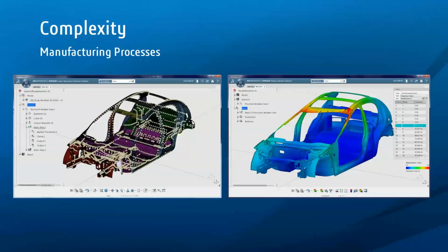Manufacturing processes can be multi-step dynamic operations. They can involve material manipulation or the connecting of components through many means. With SIMULIAworks, we're able to simulate a suite of connections, from general ties and couplings to simulating virtual bolts, welds, and general connectors. These general connectors can be based on templates, or they can be defined by the user for a complex relationship. Connectors can be defined with their own rigid, elastic, or nonlinear properties to accurately simulate a real connection while minimizing computational expense.